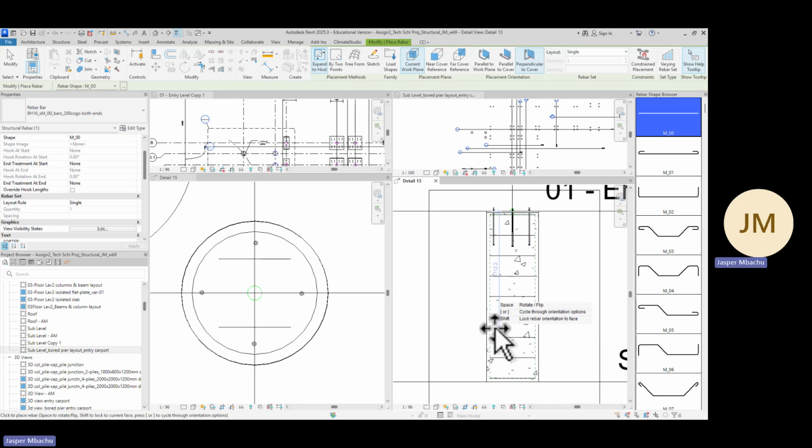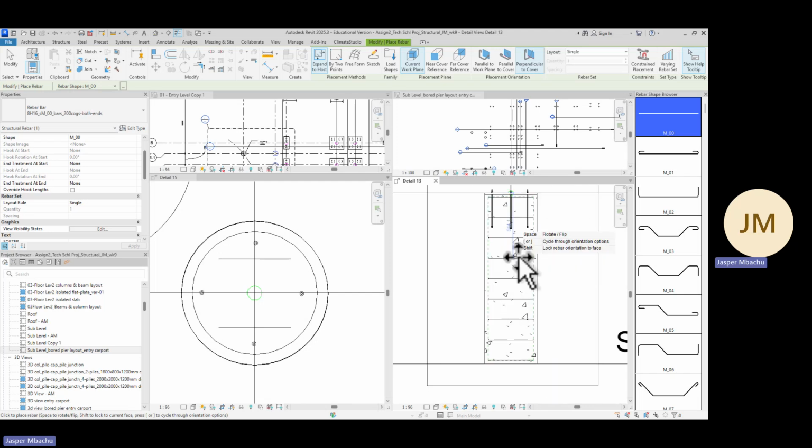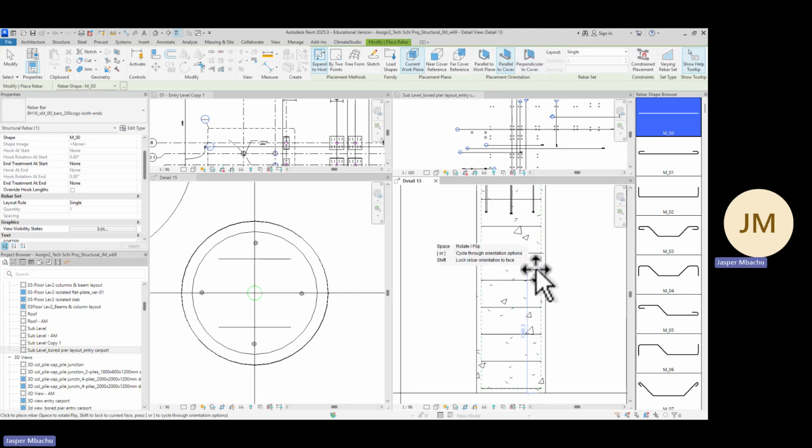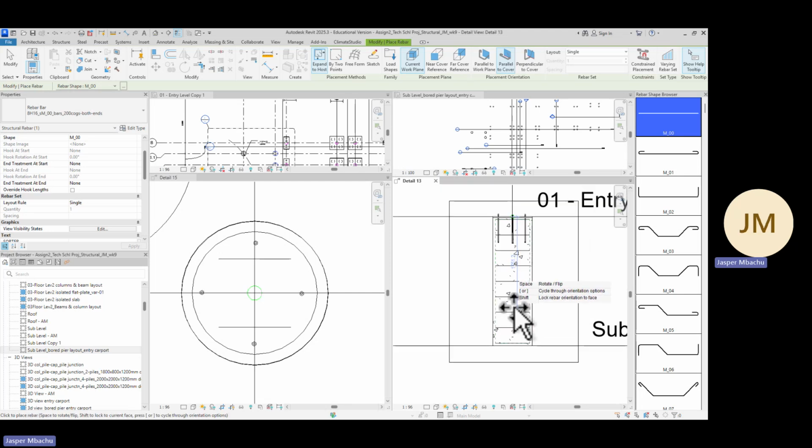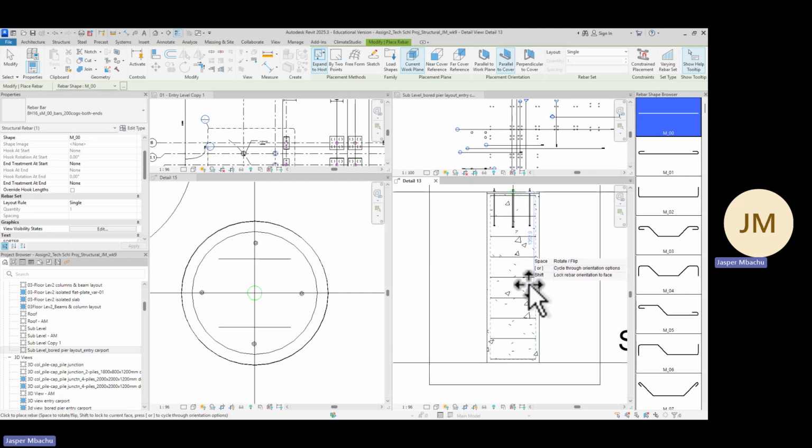and when you bring the bar to this section, you could see it wants to place the bar, but in a wrong way. You keep toggling. Let's choose parallel to cover. Anyone that you choose, and it shows a vertical line, it shows it in a strange way. You may not actually see how it is displaying it, but keep toggling until you see a vertical line. So I chose parallel to work plane. This is the one I chose, and it showed a line.